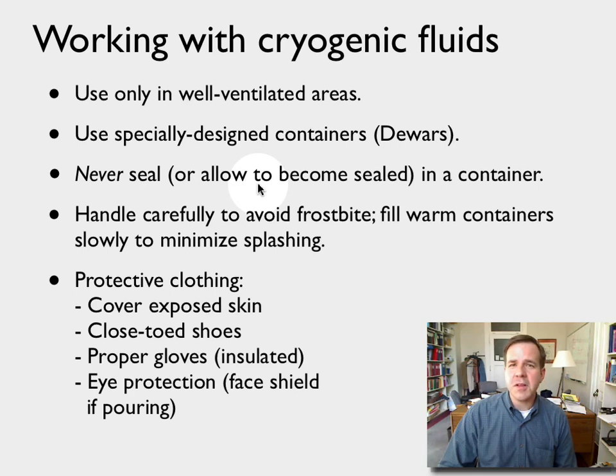As I mentioned, for the cylinder at Texas A&M, someone unauthorized, without apparently understanding the risks associated with what they were doing, had replaced the safety devices, the pressure relief valve and the rupture disc, with brass plugs, and that's what allowed that pressure to build up in that case. But pressure can also build up in sort of unexpected ways. For instance, if you get condensation that freezes, it might freeze off a vent, and it's possible for pressure to build up for that reason as well.